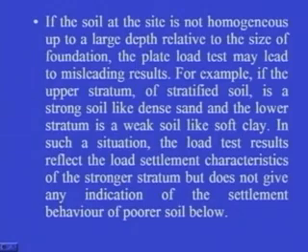If the soil at the site is not homogeneous up to a large depth relative to the size of the foundation, the plate load test may lead to misleading results. For example, if the upper stratum of stratified soil is a strong soil like dense sand and the lower stratum is a weak soil like soft clay, in such a situation the load test results reflect the load settlement characteristics of the stronger stratum, but do not give any indication of the settlement behavior of the poorer soil below.